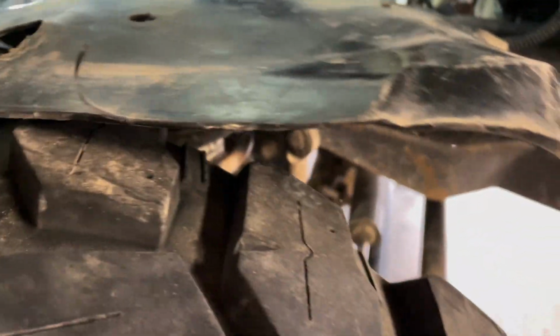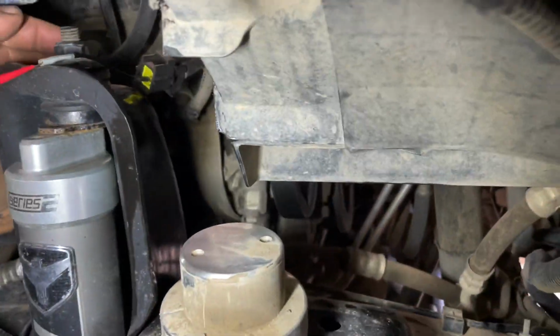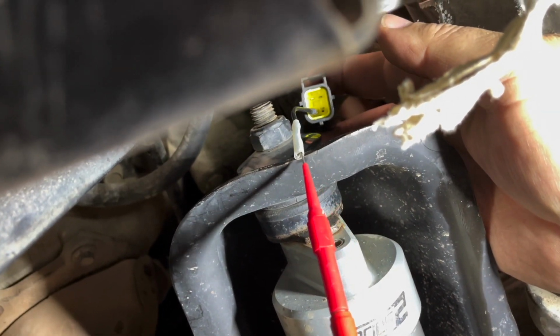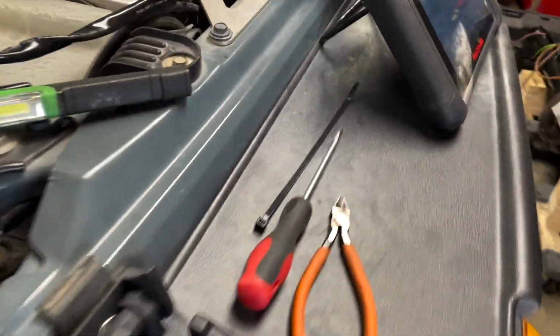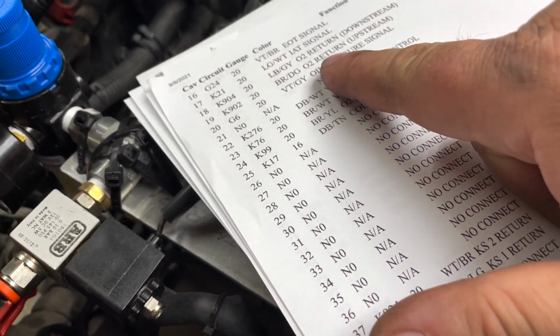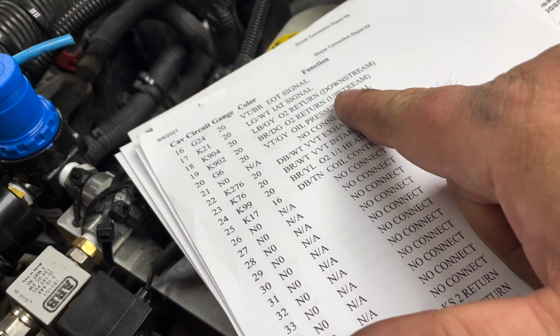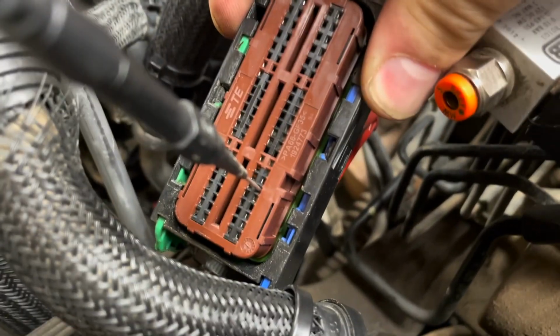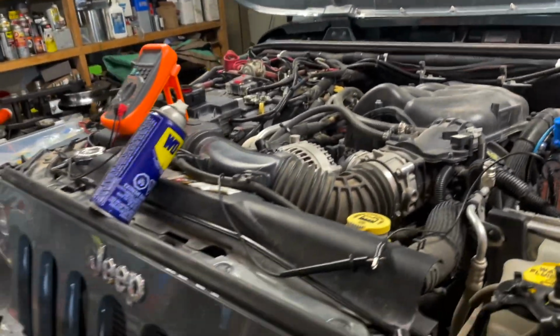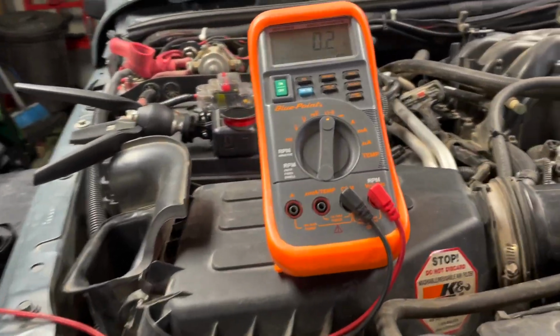So now going back to the O2 sensor wiring harness, you're going to see I have my jumper plugged into pin number 3 right there. Going back over to the C2 wiring harness or the connector, looking on my sheets, pin number 19, O2 return signal. And you can get a good look at it right there. Everything's looking good. Go to the meter. And you're going to see I'm not over 5 ohms, so I tested good.